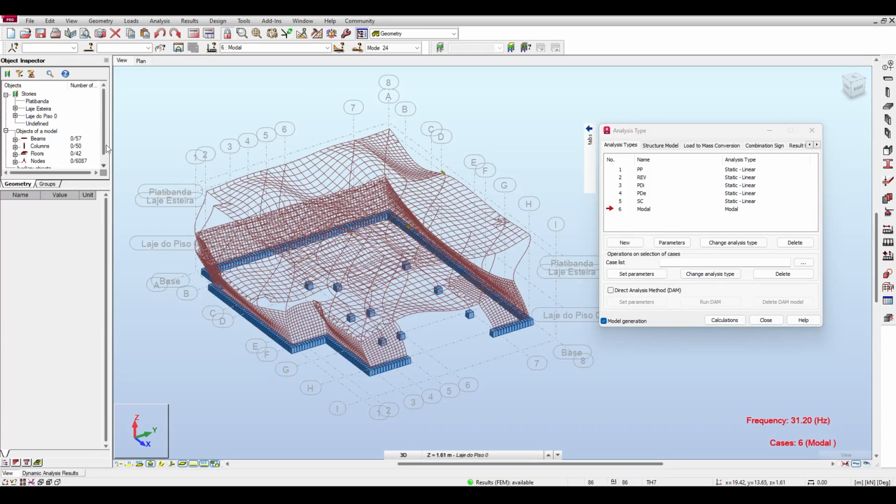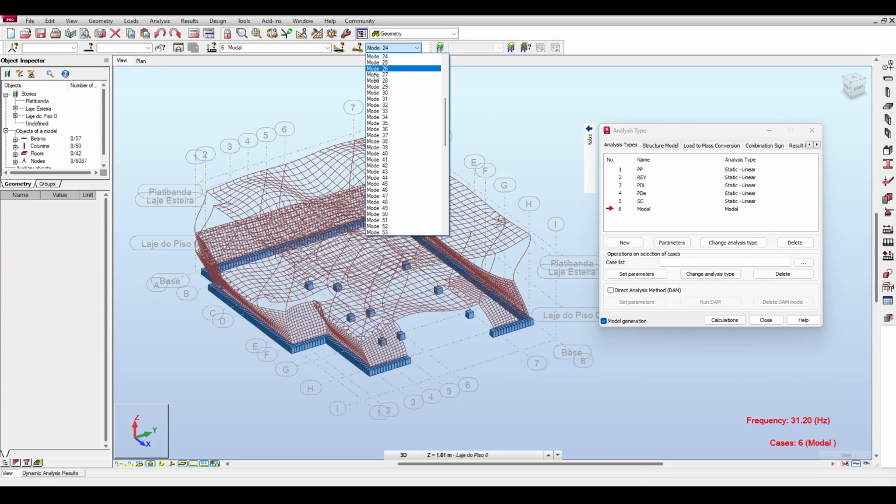I mean, rotating machinery, like sieves or crushers, might have a frequency in the ballpark of 10s and 20s, not 31s. So, yes, the structure can vibrate like this. That is true. But the question is, what kind of significant force would have a frequency of 31.2 Hertz? Okay, you could still defend this, but what about this mode, 34? This mode, 34.